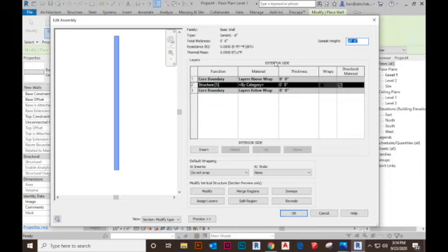Notice on the top of this field, the exterior side refers to any layer above this top core boundary. The interior side on the bottom refers to any layer on the bottom side of this core boundary. Anything located in between the 2 core boundaries is considered a structural element. That is where your true structure of any wall system should live. Everything not a structural element, such as a finish or a substrate or a thermal or air barrier, should live on the outside of those core boundaries.